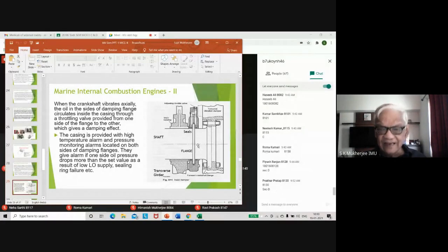So it's a thin layer of oil which is being compressed. It is not a massive volume of oil that is being compressed. It's a thin layer, even thinner than the thickness of the flange. So that thin layer of oil which is compressed will have a tendency to go out through the orifice or come back through the orifice. If it moves in one direction, oil comes in. If it moves out, it is again compressed to be pushed out.